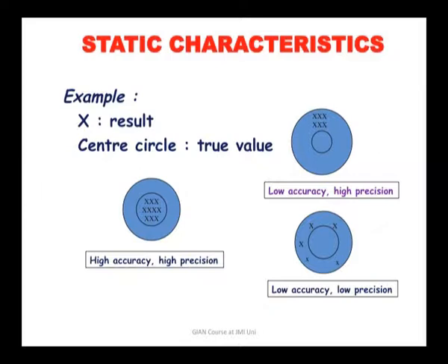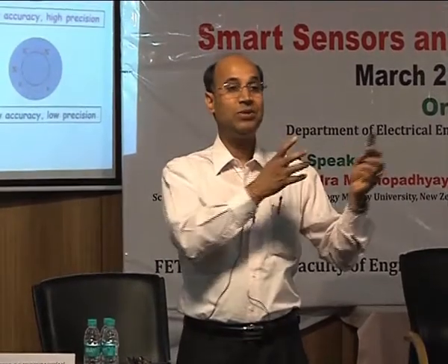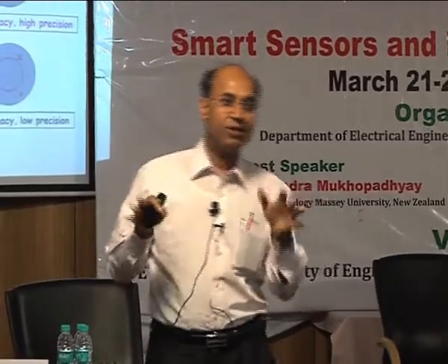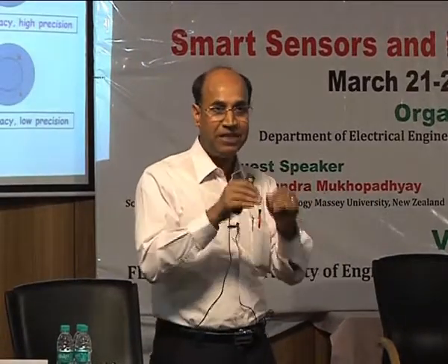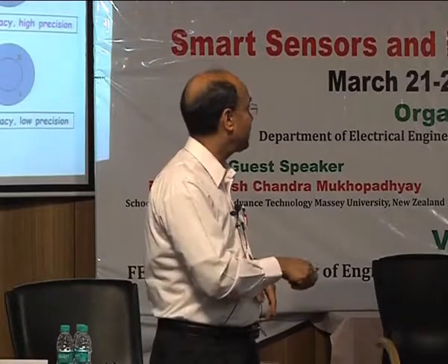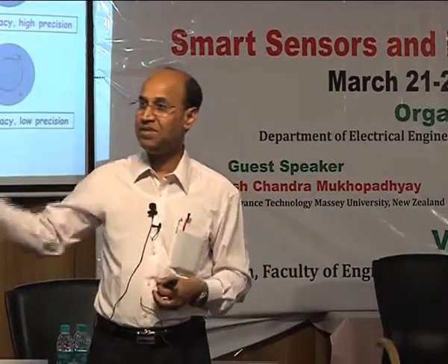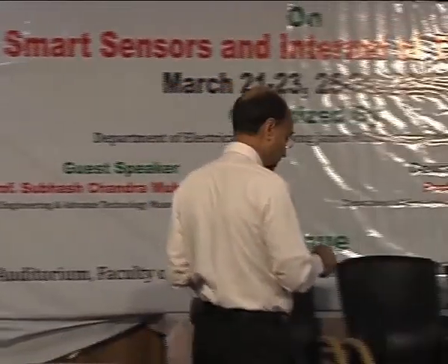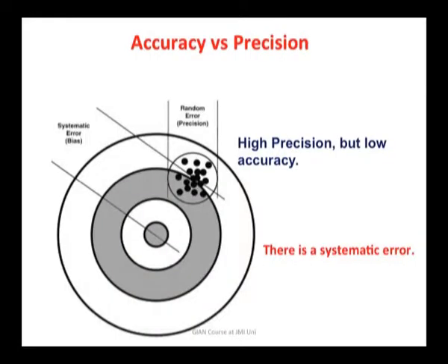But out of these two, it depends on whether somebody is looking for the precision or somebody is looking for the accuracy. In fact, maybe in this one, you get accuracy that is maybe good, a little bit higher, but if you say precision, it's not as good. Okay? So sometimes it's a little bit confusing, but precision effectively means, I mean, some books maybe don't say precision, they may say repeatability. Okay? That's the term they use, repeatability, which is quite common.